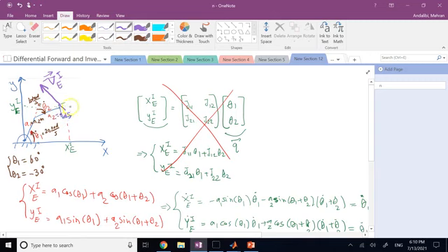Okay, and the main reason it is moving backwards is this theta 1, which is dominant, 20 instead of 10. So this is the total resulting velocity of the end effector due to both of these motions at the same time. So you can change any number that you want. You can change the configuration. That will lead to a change in the end effector velocity. You can change the rotation velocity, the angular velocity of the members. That will also change the number here, right? And you can change the geometry.